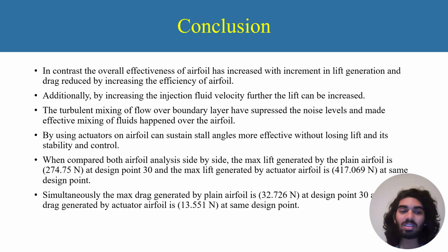The maximum lift for the plain airfoil is 274, whereas for the actuator we got 414, which is around a 50% increase. Whereas the drag for the plain airfoil is 32, whereas the actuator case is 13.55.